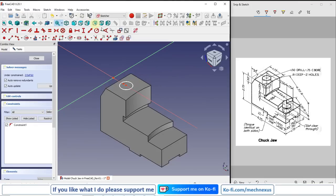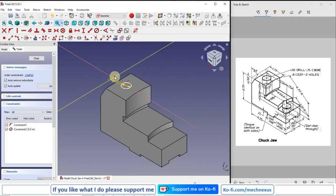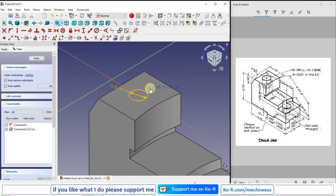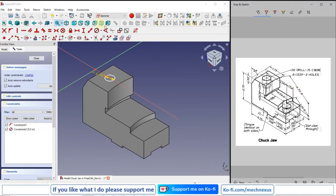So now here we have 0.5 drill, so I will select this one and I will go for diameter and I will give 0.5. Now the position of this hole is a 0.25, 0.75. So I will project this edge here, and then I will select this point and my center point.